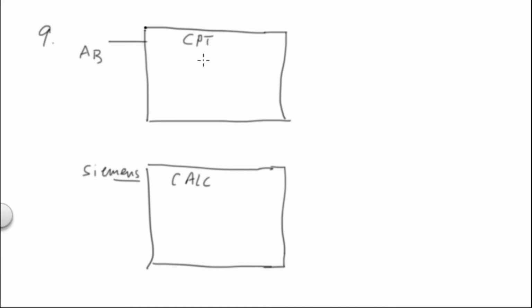So you can do it as a multiply block or as a calc block, and I like the calc and the compute block because it's pretty simple. With the compute block, you write it in here as an expression: widget count accum times 0.35, and then it comes out here as the total.